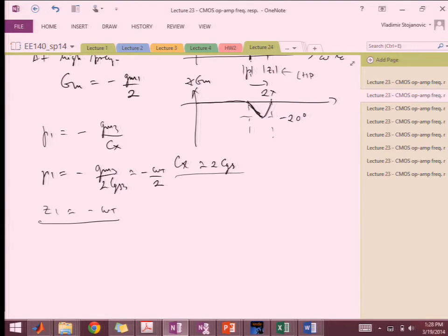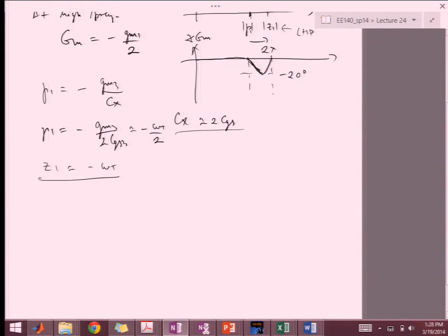But in some configurations where we're pushing the unity gain frequency close to that, they can start playing a role as a third pole and another zero that sits right next to it. So in configurations with these single-ended differential pair structures, you need to start worrying about this as a third pole, especially in Miller compensation when the second pole starts shifting, so this doublet starts playing a role.